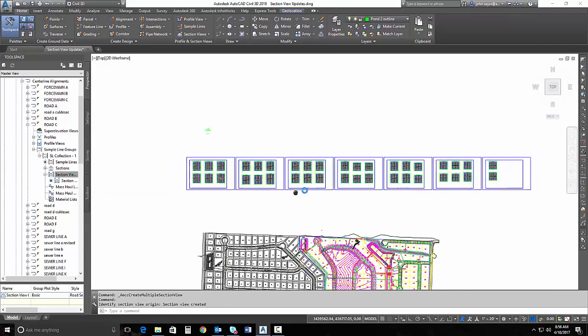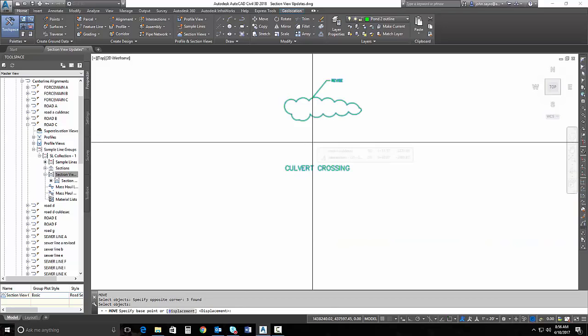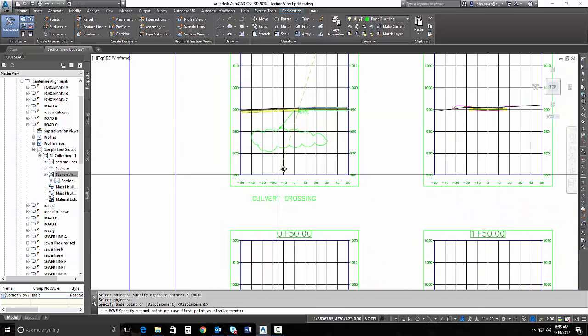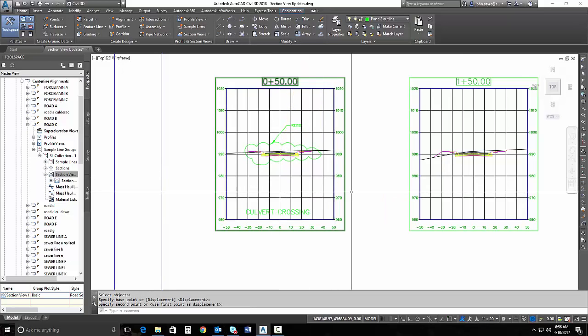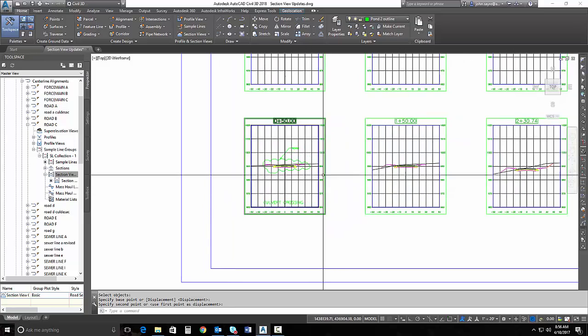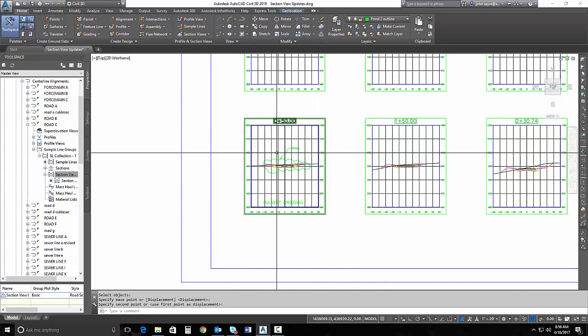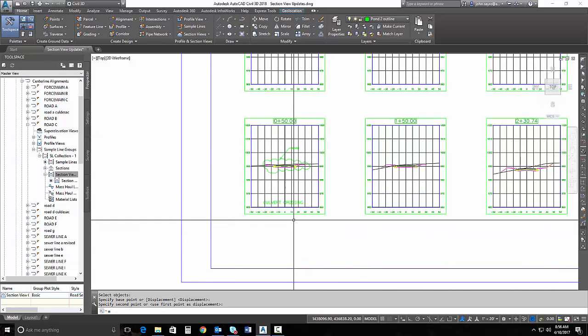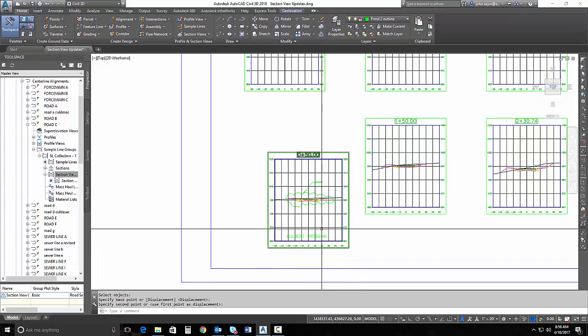All right. So here's a copy of my section views. All right. So to show you this, I'm just going to move a piece of line work and some text into this section view. All right. Now, what I'm talking about, what the benefit is of this actual drafting buffer, is that when I move this section, this text and everything will go with it. So if I just move this cross section to here, all of my manual text goes with it.